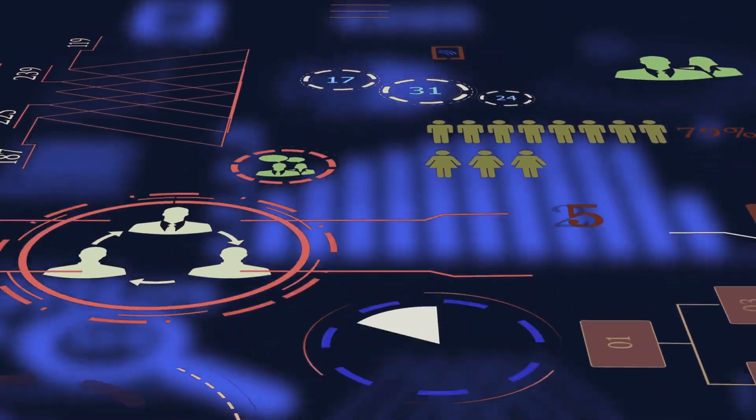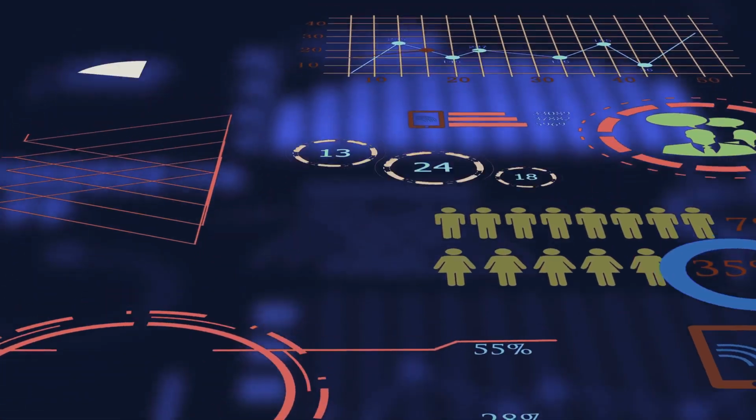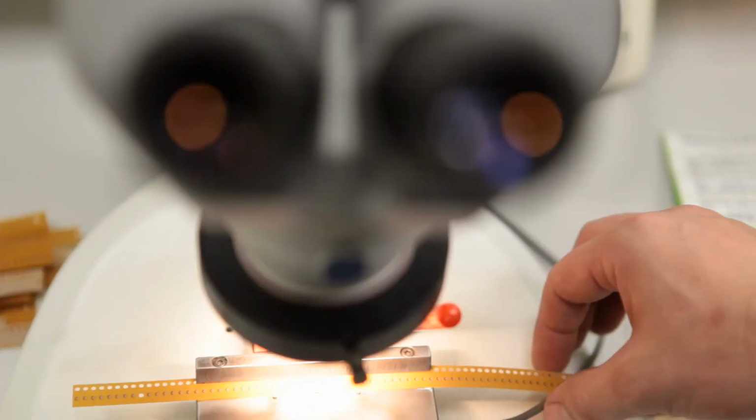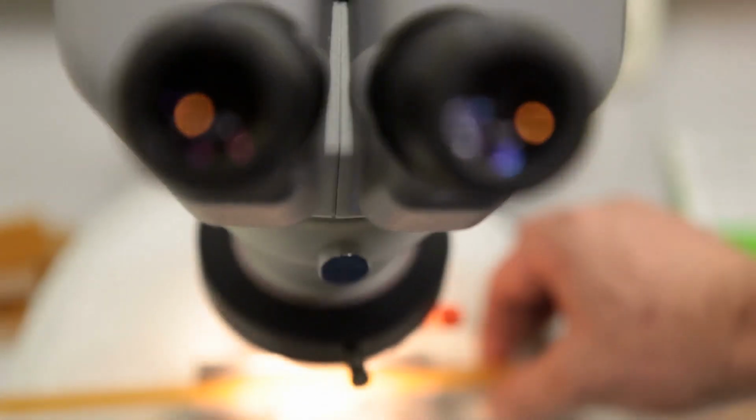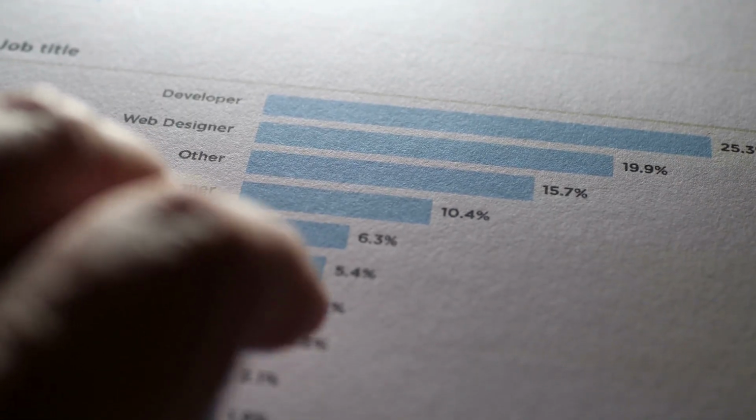The second major step is choosing the right control chart for each of your metrics. A P chart is for monitoring proportions like the percentage of defective products. X bar and R charts are for monitoring averages and ranges in continuous data. C charts are used for counting defects in a fixed sample size.